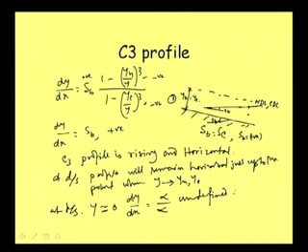But you must remember one point, that this is when depth is just equal to 0. When y tends to 0 but is still not 0, the flow profile remains horizontal. Only when we try to express it mathematically do we find difficulties about what will happen just at y equal to 0, but from a physical or real situation point of view, we will not get that sort of situation.